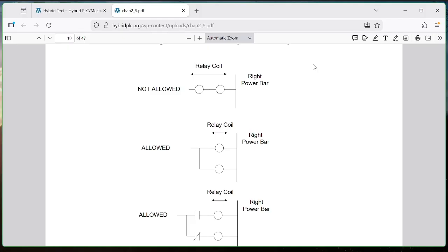You would split it 50-50, okay? And the relay will not turn on with 6 volts. It might turn on with 9 or 10 volts, but not with 6. Everybody follow that? But in a PLC, they allow it. So you can't see this in the real world. You can see this in a PLC, because they'll let you put 10 of them in a row if you want to. Now, they mean the same thing.